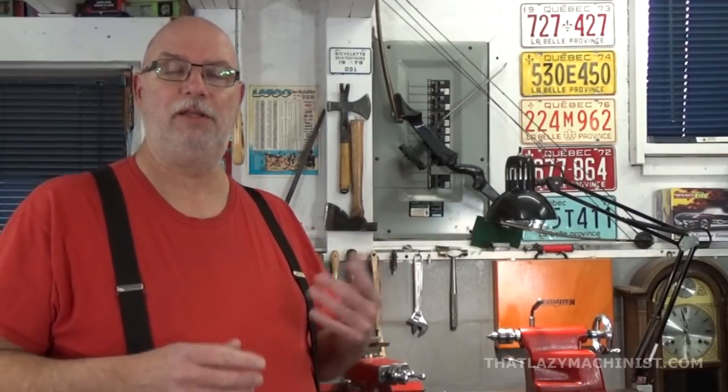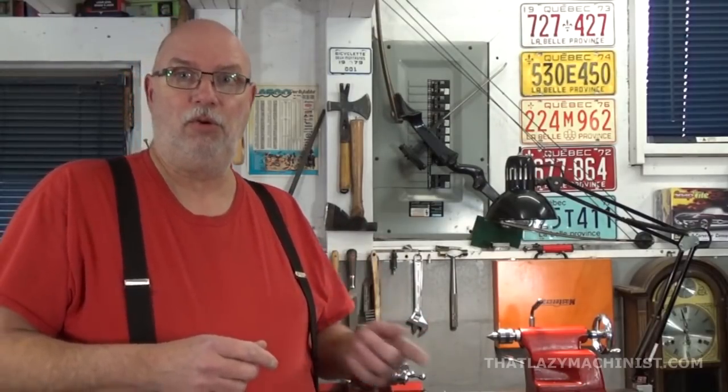So I'm going to want to turn the small diameter first, but there's a problem with that. I can't just cut it in one fell swoop. Now why is that? Well, the chip is going to be quite wide. Now I can give all the back rake that I want. A chip that wide is going to have one edge much longer than the other. I mean, the edge that's going to be on the 1/2 inch diameter side and the edge that's going to be on the 25/1000ths of an inch side are going to be very, very different in length.